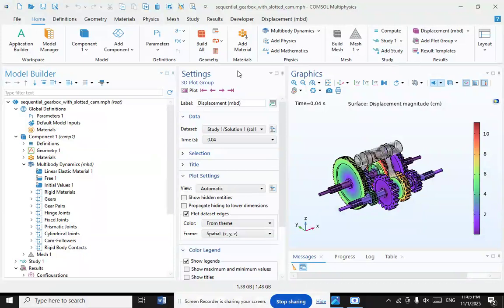And what about the non-synchronous transmission? Another design of transmission that is used in older cars, trucks, and tractors is a non-synchronous transmission, also known as a crash gearbox. Non-synchronous transmissions use a sliding mesh or, in later years, constant mesh design, and have the nickname crash because the difficulty in changing gears can lead to gear shifts accompanied by crashing, crunching noises.